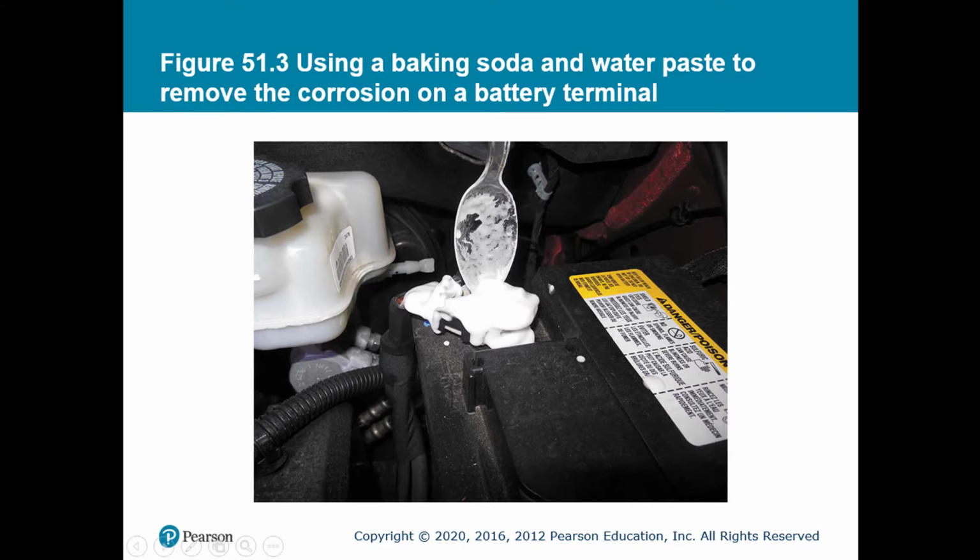The aftermarket replacement terminals are not usually recommended for a good factory repair. They actually want you to replace the entire cable. And it might be worth doing because if that cable does have corrosion in it, that will create a voltage drop due to the resistance in the cable. So you could put all the fresh batteries you want, it won't make a difference. So the big problem, or the bigger problem, could actually be the cable.